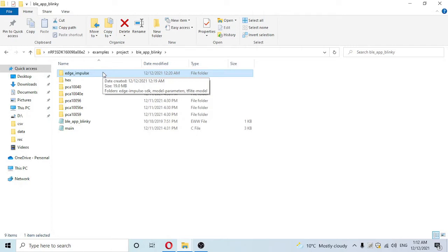Let's say it wants to print classification results, or another example, let's say it needs to dynamically allocate memory for its internal uses, and Edge Impulse library is not aware where it is being run. So for instance, you may run Edge Impulse on a Nordic semiconductor microcontroller, or you may run it on a microcontroller by Texas Instruments, and each of these microcontrollers have different function calls for printing stuff or for allocating memory.